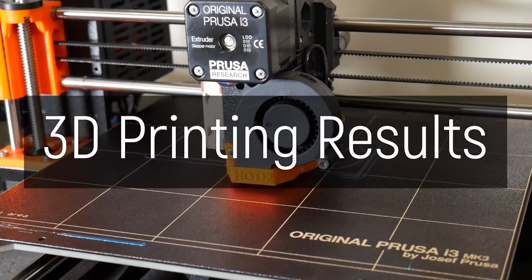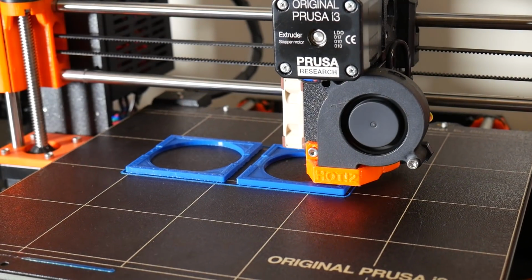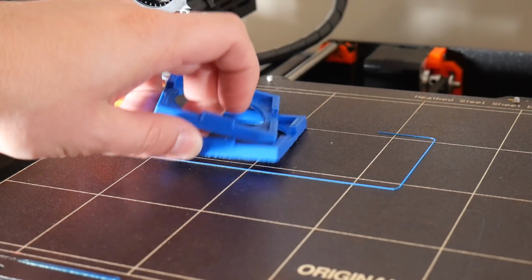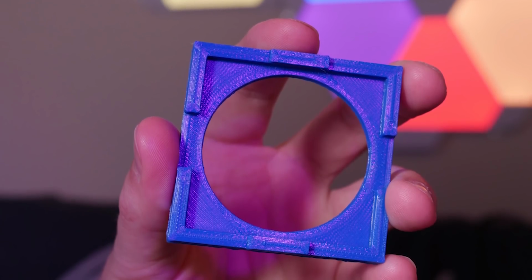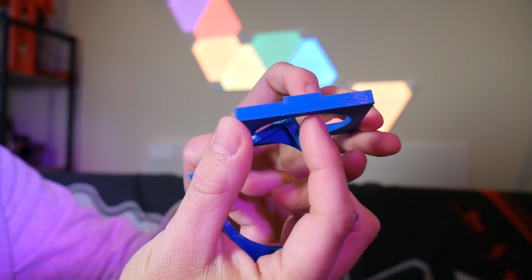Alrighty, so how did we do? Well, I kicked things off with the IKEA dimmer adapter thing, and it printed out as you would expect, pretty much perfectly. The extra perimeters give it lots of strength, and it actually doesn't need too much infill, so I think this one had no infill really, it's pretty much solid plastic.